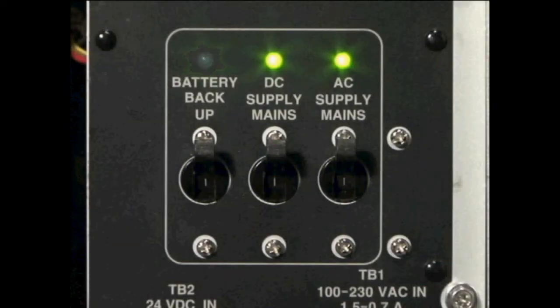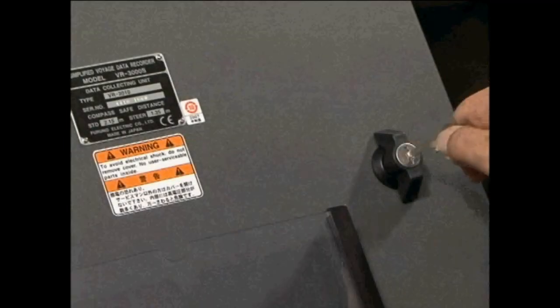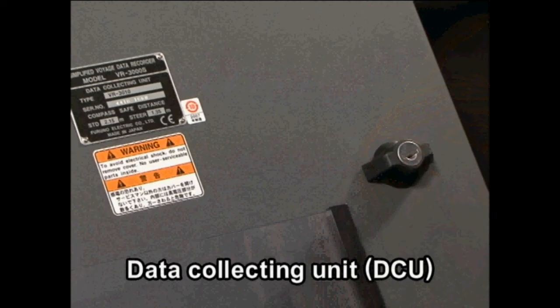The VDR system remains switched on and continues to record data until the ship's power supply fails. As such, there is the risk that data recorded at the time of accident may be overwritten and updated by new data. Access to the DCU is simple, but is limited to those in authority with a necessary key.